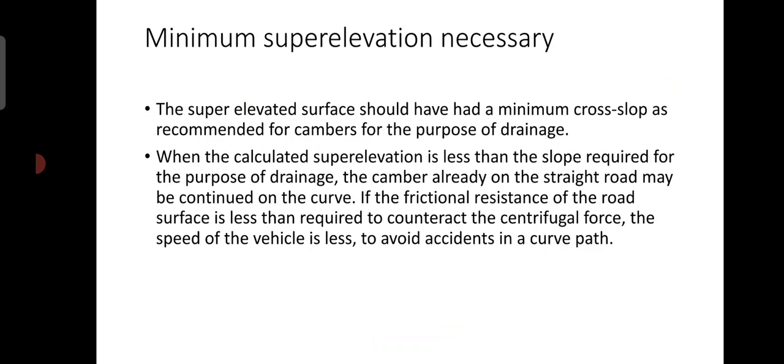What is the minimum superelevation that has to be provided? The superelevated surface should have a minimum cross slope as recommended for camber for the purpose of drainage. So the minimum superelevation provided is equal to the camber.